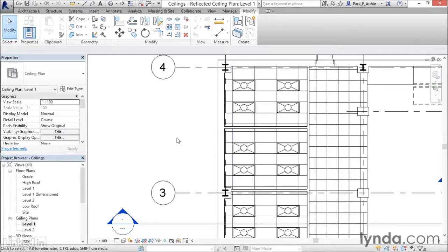But in cases where you have a more complex ceiling, you can always switch over to a sketch mode. If you've got a grid pattern assigned to that ceiling, you can move and adjust it just simply using move and rotate. And placing light fixtures are useful to help you make decisions about exactly what orientation you want those grid patterns to have.